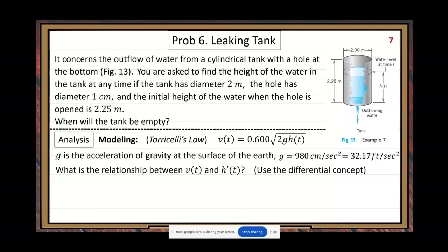Do you want to represent the distance of the water flowing out? So v of t times time t, or delta t, right? Because it flows out in a small amount of time, so use delta t to measure this distance, the length. You know the area, right? Can you calculate the volume? You have the length and the bottom surface. Can you calculate the volume of the water? This much volume. And in the tank, the volume reduction, can you equalize those two amounts? Think about that. That's the equation we want to establish.